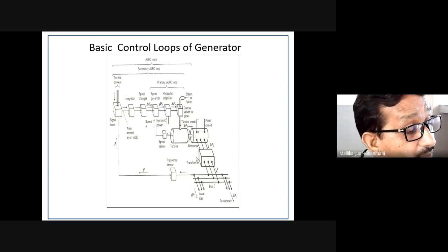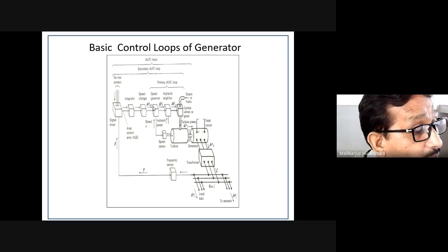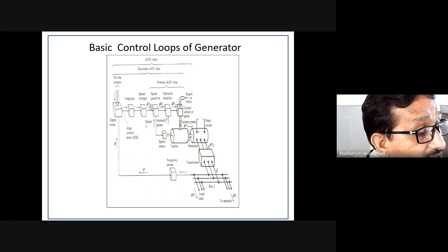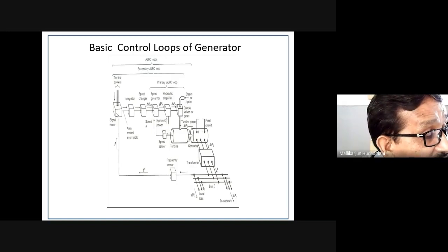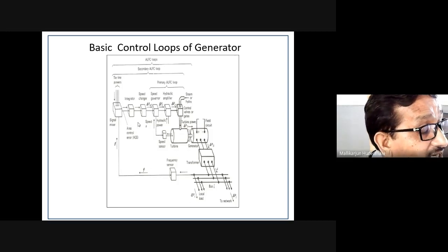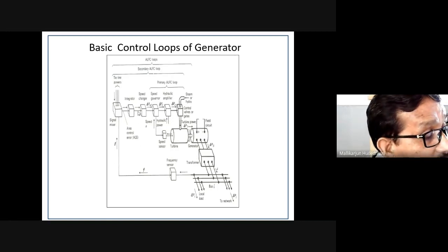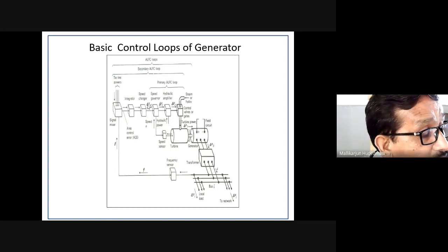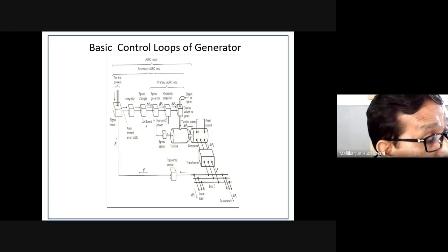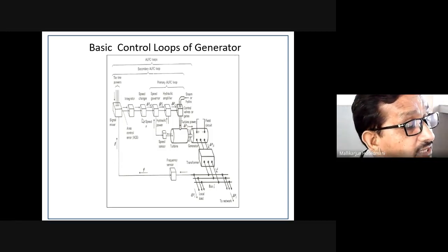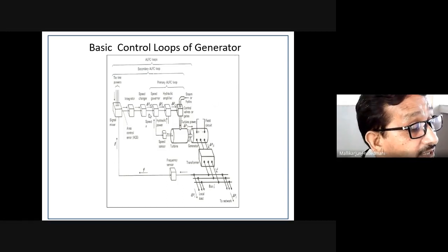It may bring your requirement. In this way, the governor's set point is changed by the speed changer mechanism. This speed changer will modify the set point only after the signal mixer and understanding the error of this locality, called ACE. ACE being brought to 0, whatever output is available makes the speed changer respond positively to increase the set point or to decrease the set point.